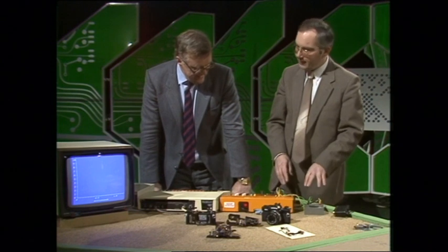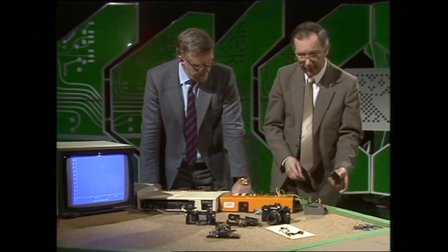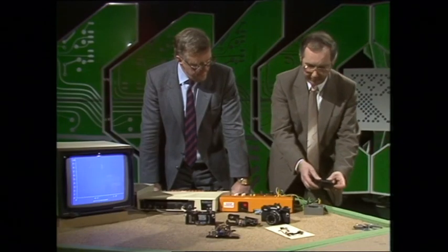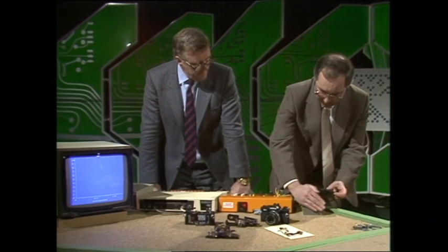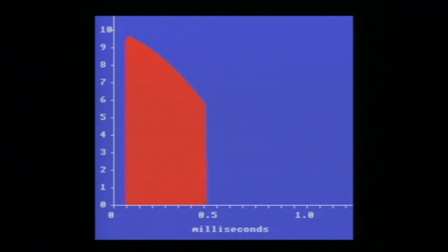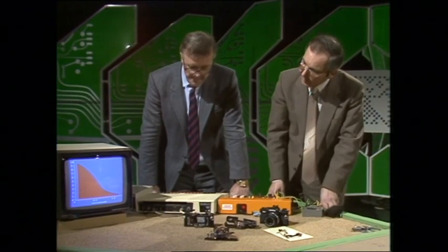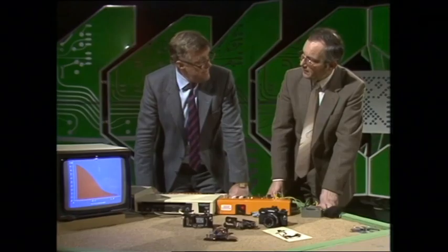But this time, we can set it up so that we take samples of the light intensity landing on the photocell. I've got an electronic flash gun that gives a very short burst of light, but if I fire that above the cell, we'll see on the screen in a moment a graph showing the light intensity. I'll just shade it from the studio lights, fire. Now, when I fire it, the computer grabs 256 samples very, very rapidly, but then it displays them on the screen somewhat more slowly. In a moment, it's finished now. And that's about 1 millisecond, a thousandth of a second that it's displayed there with all the sampling that's gone on in there. Right. That's beautiful.